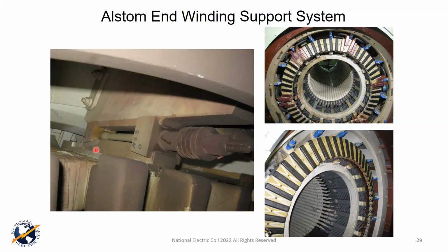I used to call them scissor jacks, because they have this rod that pulls these two blocks that are on a taper together, which exerts pressure between this block out here and the support that's on the back of the winding. Now that rod that goes all the way through there, it's threaded here at the end with that nut. And this is actually a stack of Belleville washers.